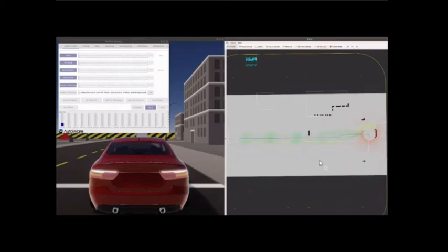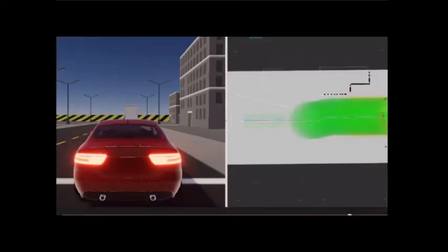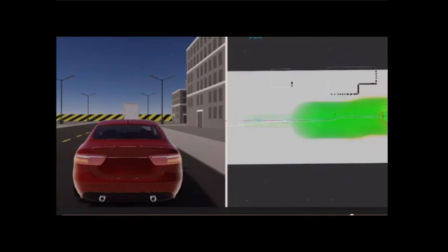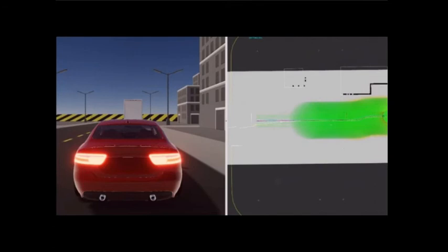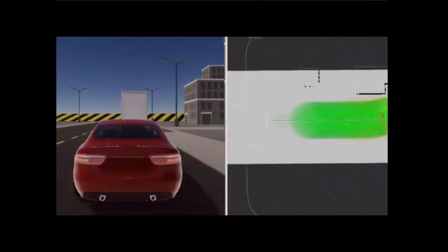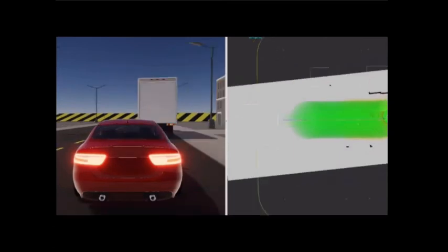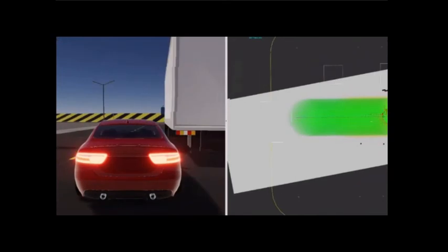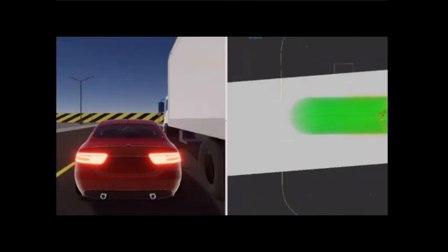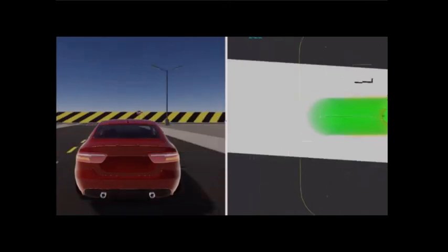I tested the hybrid A-star path planner, global planner, but now with the lattice motion planner, and the behavior was quite similar in terms of lateral distance from the obstacle, but it was much quicker. The local planner calculated the road much quicker and avoided the obstacle again.